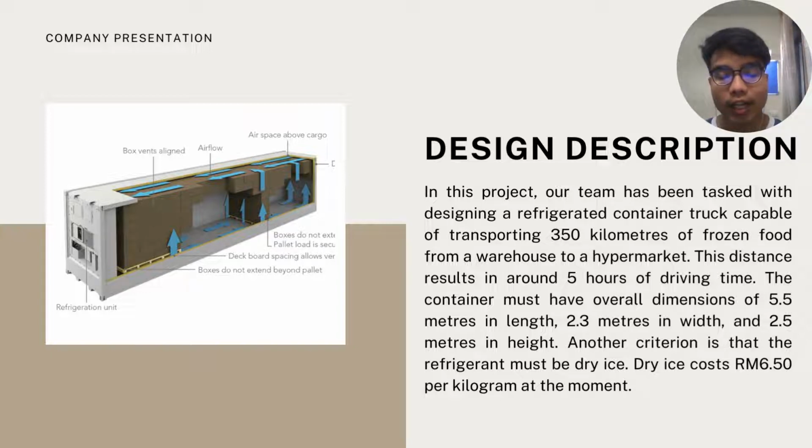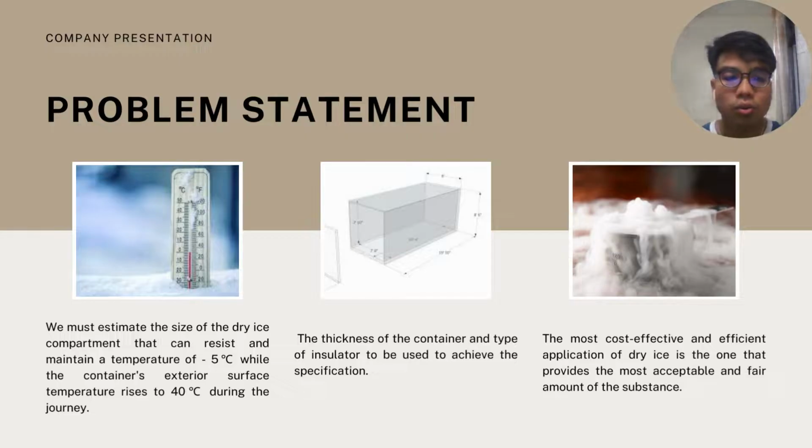So, by utilizing heat transfer applications and knowledge, we are required to come up with the most efficient design to prevent food from melting and spoiling during transit. The problem statement for this project is: assuming the design capability, we must estimate the size of the dry ice compartment that can resist and maintain a temperature of negative 5 degrees Celsius while the container's exterior surface temperature is at 40 degrees Celsius during the journey.